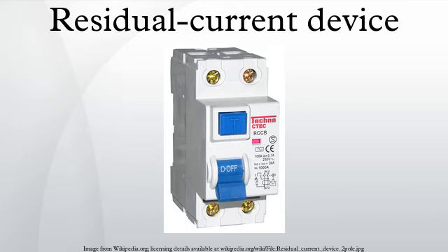Australia. In Australia, residual current devices have been mandatory on power circuits since 1991 and on light circuits since 2000. Europe. Belgian domestic installations are required to be equipped with a 300 mA residual current device that protects all circuits. Furthermore, at least one 30 mA residual current device is required that protects all circuits in wet rooms as well as circuits that power certain wet appliances. Electrical underfloor heating is required to be protected by a 100 mA RCD. These RCDs must be of type A.